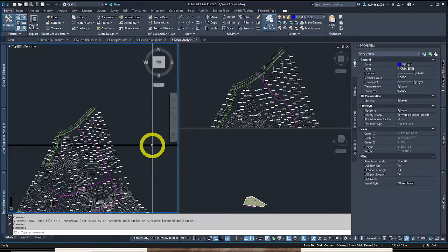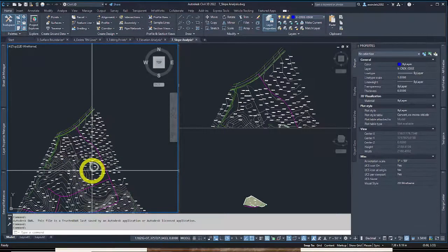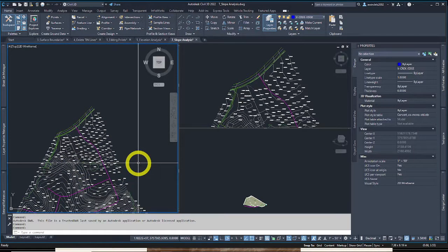Certain areas it's such high construction, and to see hydro analyses of surfaces, various things, you want to have an analysis of where the slopes are the flattest, 0 to 5%. Anything over 20% you want to be defined. So there's a lot of reasons you want to show where the steepest sloped areas are to avoid on a land development project or land in general.